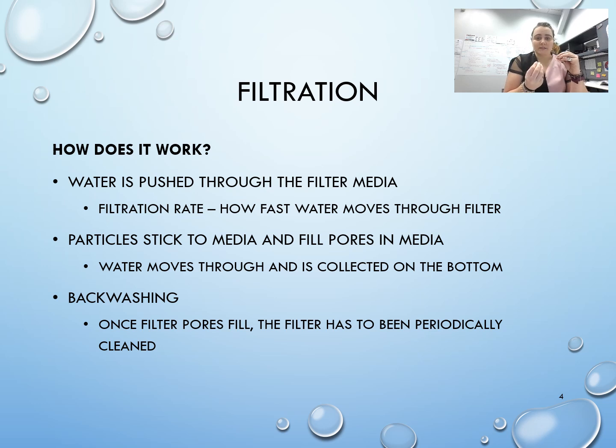So as those pore spaces fill up, we have to make sure that we can clean those pore spaces out, and we do that through a process called backwashing. So with backwashing, we have to clean that filter by moving water through the bed. And we'll talk about this a little bit more in a couple slides.